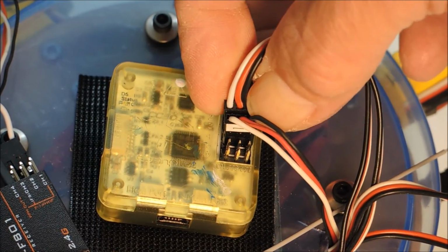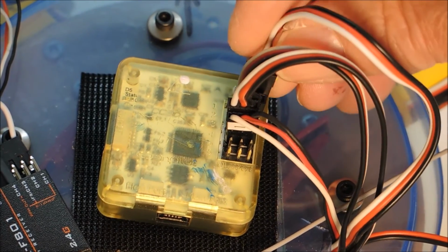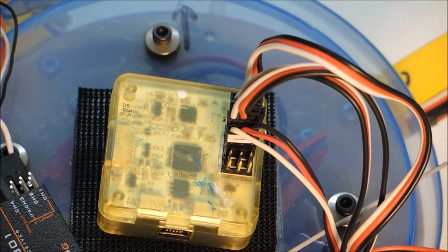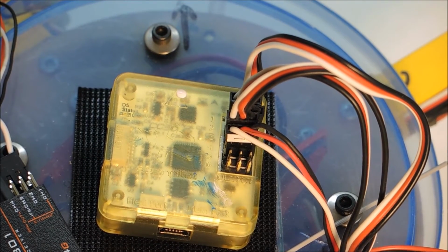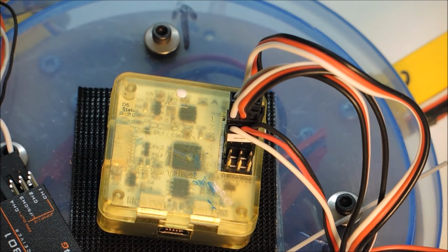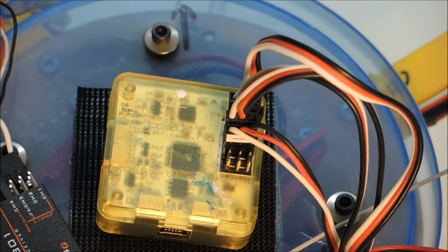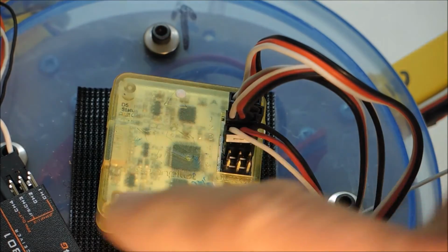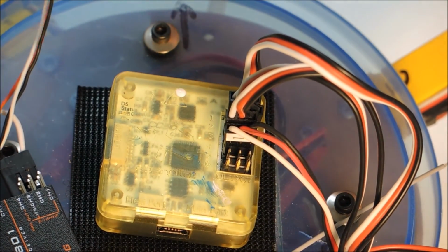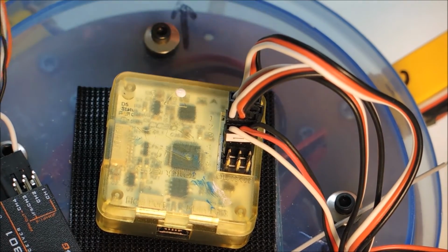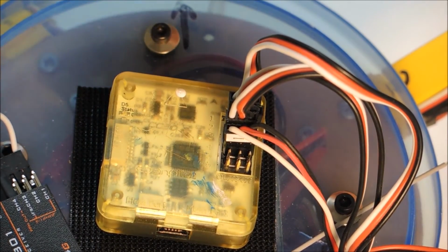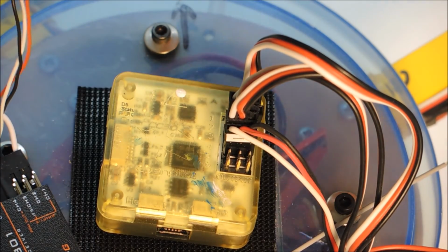Now, if you've been using the OpenPilot software, the motor layout for Cleanflight is different, so it's important that you pay attention. You can't leave these connections as they were before if you converted over from one to the other. So we are simply going to connect this in, then link it up to our software, and it will tell us which motors should be running and what direction they're in.